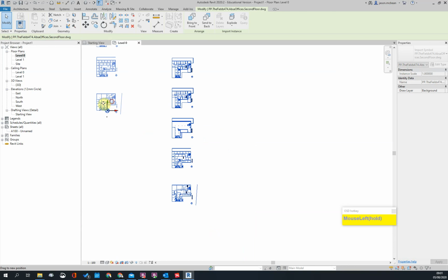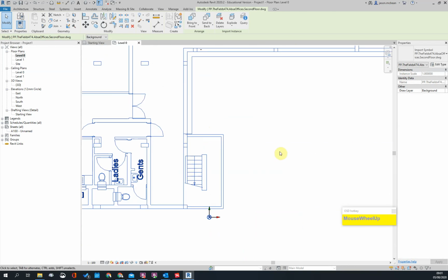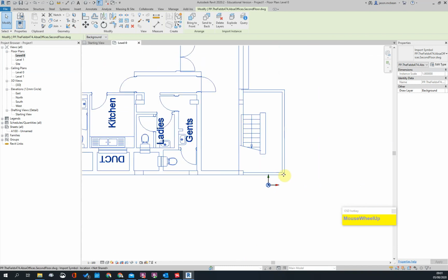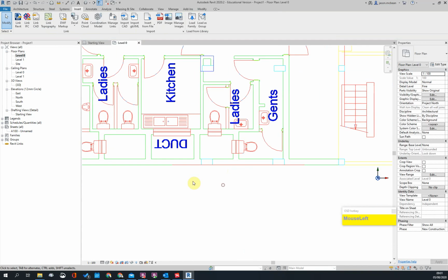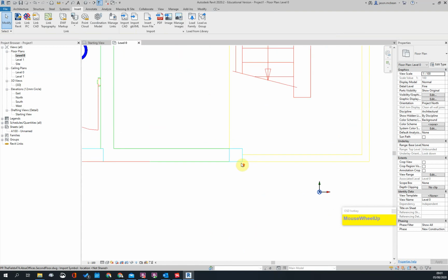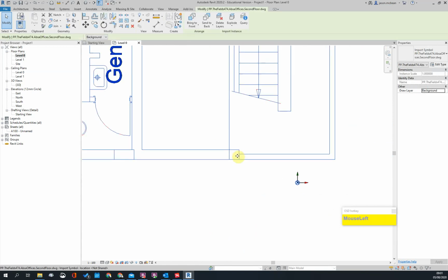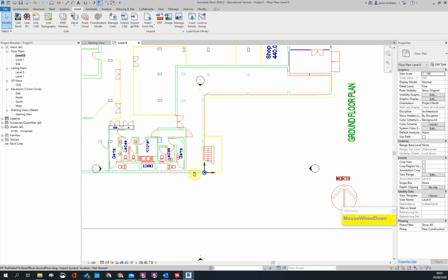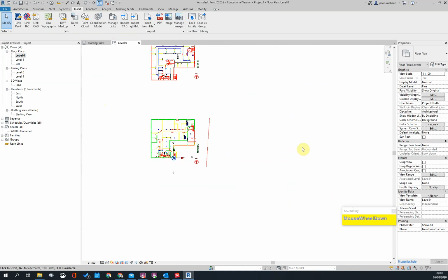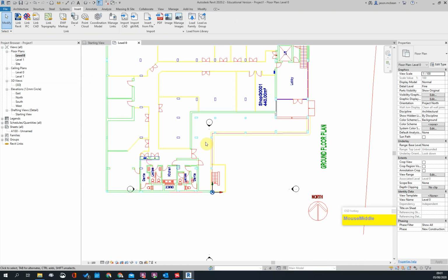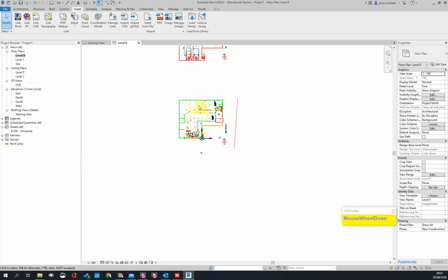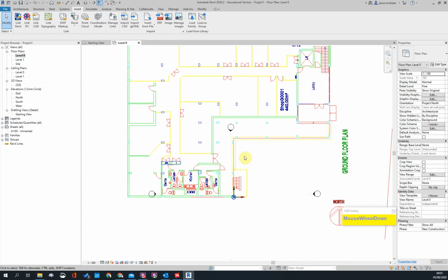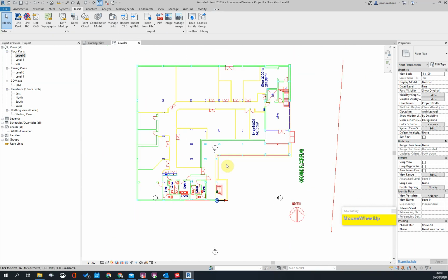Okay, move this around. So I want to find a good point to work around. I think a good origin for this project, and I can see there's some structural columns. So I'm going to make this structural column here my origin. So I'm going to move this and put this over there. Okay, great. All right, so my views are kind of getting set up. The next thing I'm going to try and do is change the color of the DWG file so it looks a bit better as well. So that's my next step.